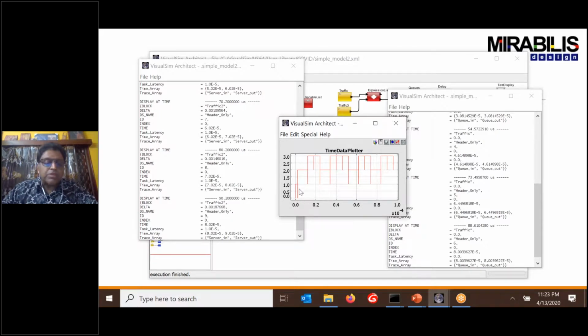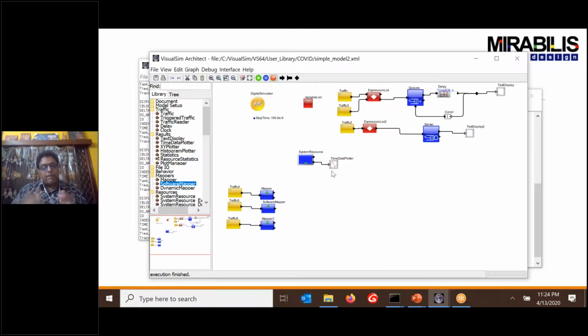So here we go. Task 1 came along, got preempted, but task 2 did not get preempted till he completed. Then 3 finished, then again when 2 came in, he could not be preempted. So if you remember the earlier one, he was crunched a little and eventually had to finish. But now, he has to complete his task before he can get on to these other things. So same model, you can have multiple flows getting mapped, you can change your clock speeds, add priority, reordering the queue, add preemption, and then add mutual exclusion for preemption. So the same set of blocks can do a variety of functions right here.